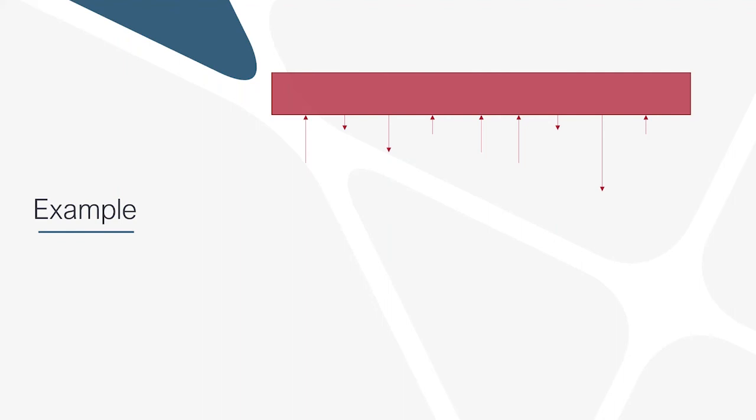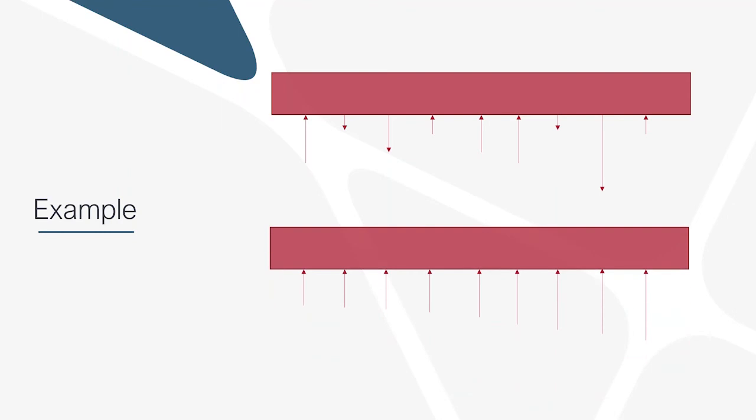I have modeled the piles as if they were fixed vertically, and just changing that one degree of freedom to be a vertical spring, which I assumed still as very, very stiff, by the way. It was essentially behaving as if it was fixed. I think the displacements were negligible, but because I made it not infinitely stiff, it allowed the structure to move just enough to redistribute the loads and ended up giving me a result that evened out. And so this is a good example of how relative stiffness can kind of create an unexpected result at times.